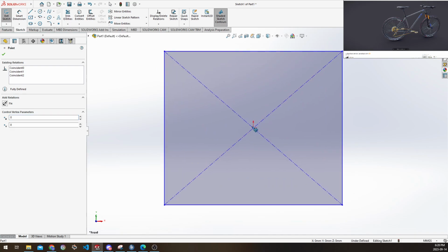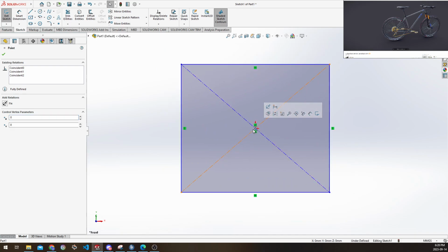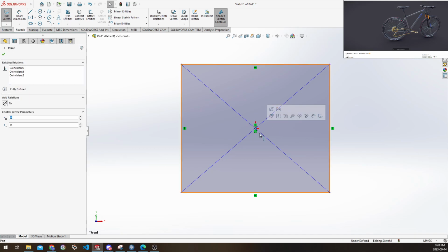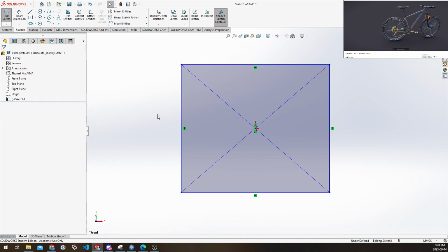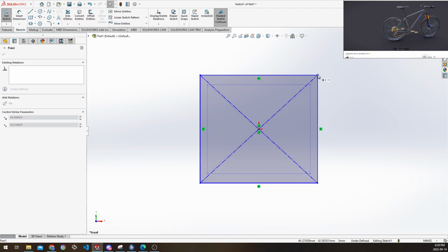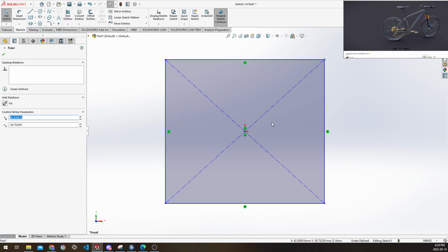Once you click on the center, you'll see a lighter version of this square, and once you move your mouse out, you'll see the preview. When you click, it'll finalize as this shape. So it automatically constrains once you click on the center? Yeah, it'll automatically make a few constraints, because this is a rectangle and there are some definitions it'll automatically make.